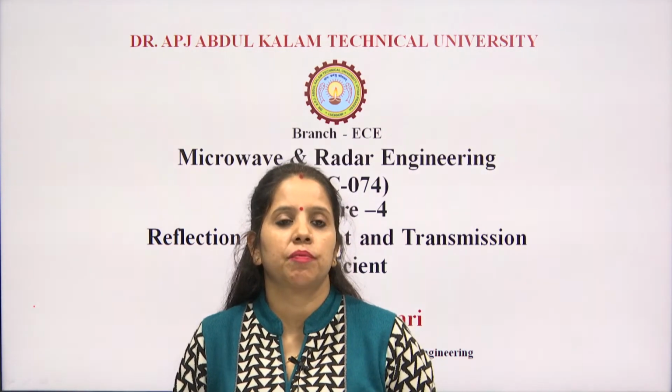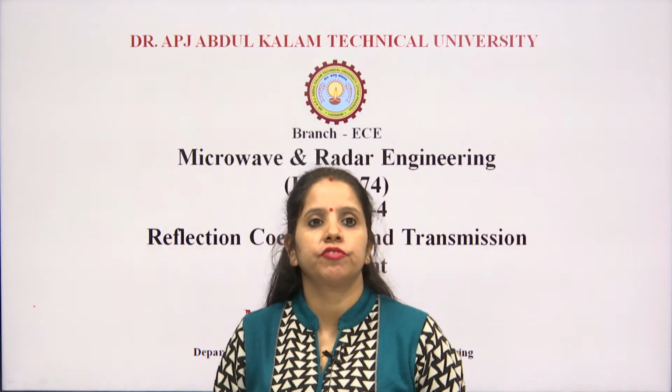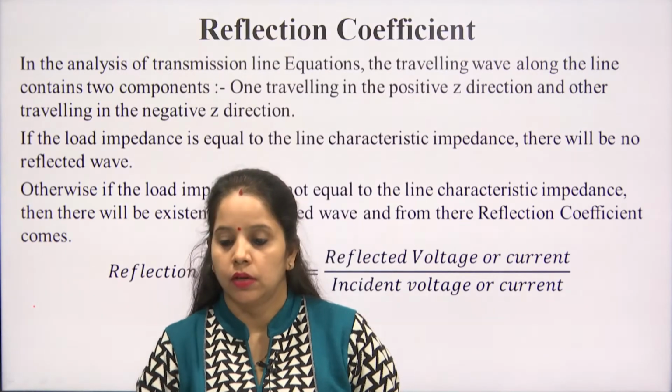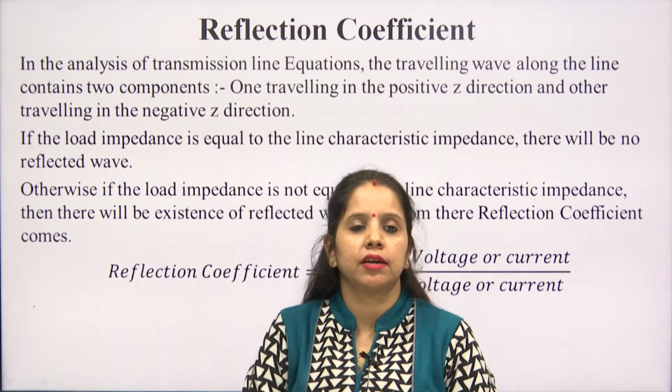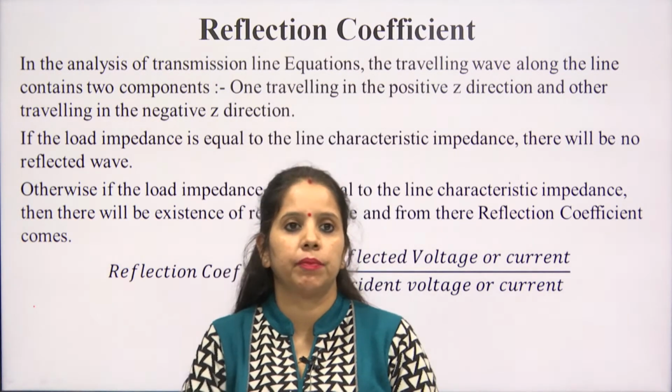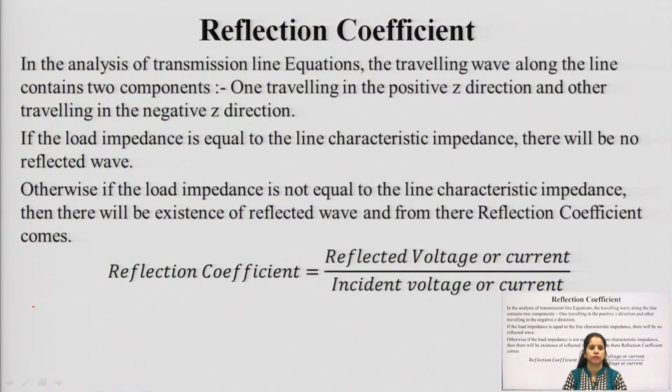Today in the lecture series of Microwave and Radar Engineering, I am going to discuss with you the reflection coefficient and the transmission coefficient with respect to transmission line. Before going towards the reflection coefficient definition, just have one brief introduction of when the reflection coefficient comes into existence. The reflection coefficient comes into existence only when there exists a reflected wave, and the reflected wave exists when our transmission line is not properly terminated.